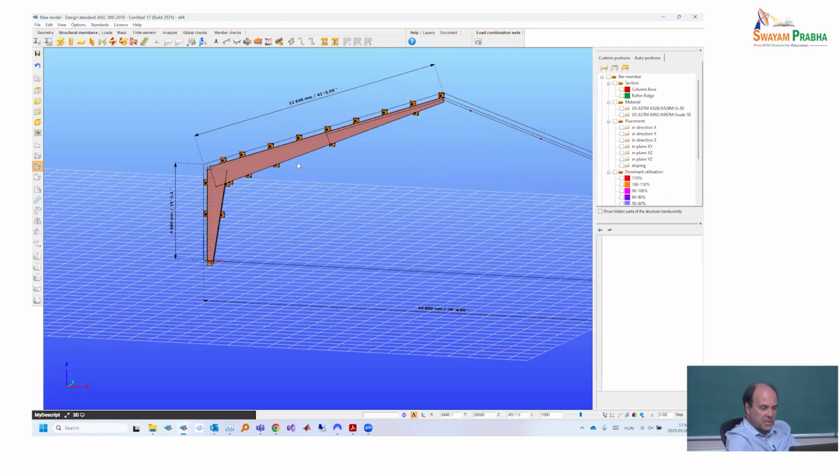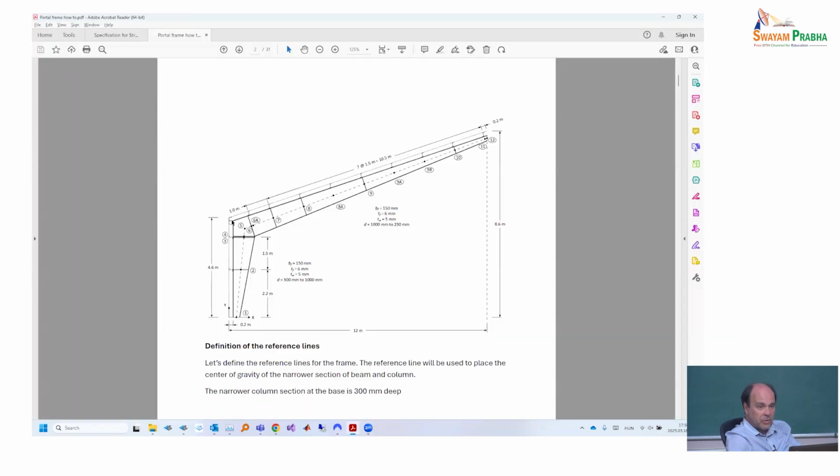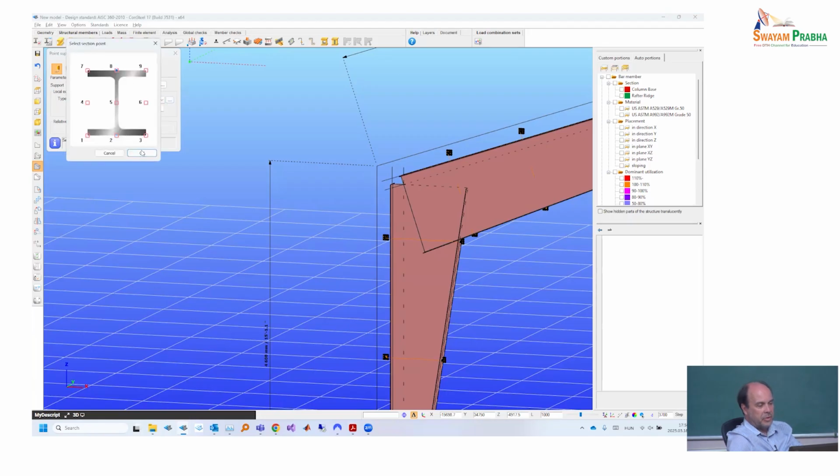Now one support is still missing. I still need to put here a support to the corner. That will be a bit tricky, but not complicated. Just again, it comes another specialty of Consteel. I come again to point support. Again, I select Y. Again, I select top. Again, I select the 100 millimeter. And normally, I click to the intersection.